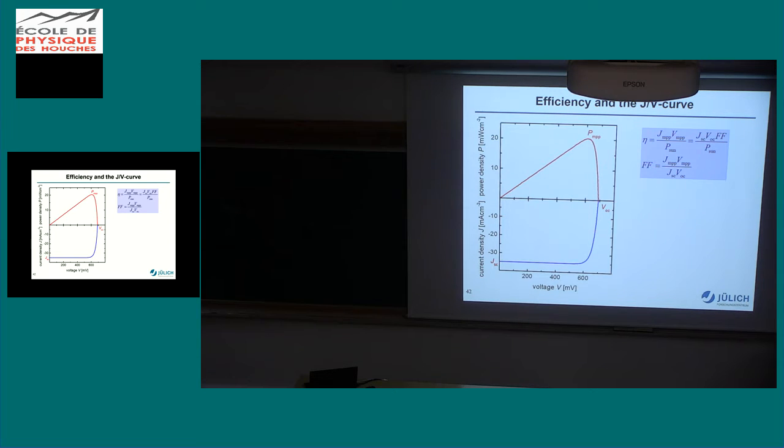That's the definition of the fill factor, and that's maybe the toughest part of understanding, because with very few exceptions, everything that goes wrong in your device, if it goes only slightly wrong, will end in the fill factor. You will not see much in the JSC, you will not see much in the VOC. Any bullshit that happens enters in the fill factor.